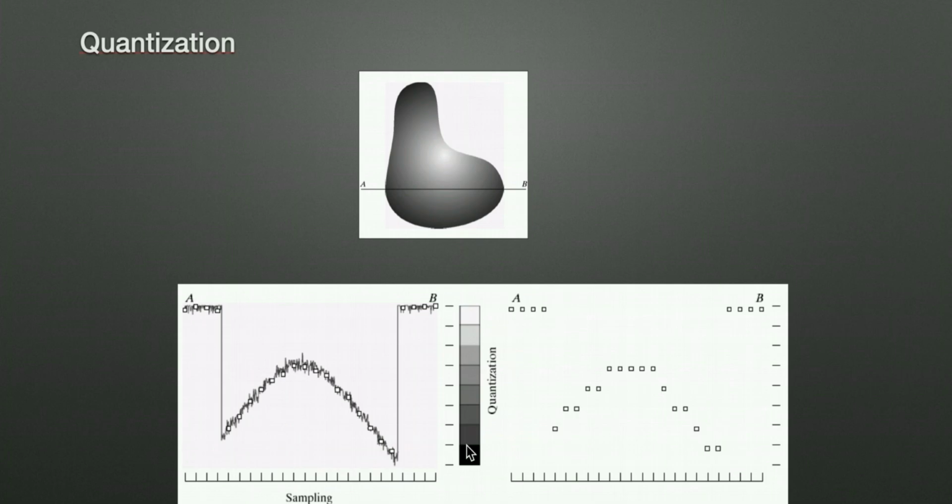That is what is known as quantization. So in sampling, you just take in points and you get the amplitude value. But after that, you need to quantize it, so that you get an approximation of the intensity values at that particular point. That is basically quantization and sampling.